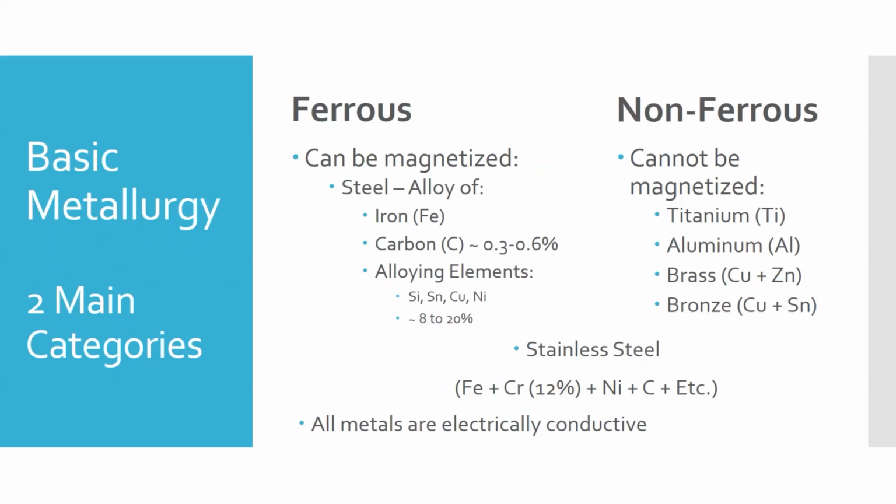Okay. But some of these will develop a temporary magnetic field during the inspection process, like when we do eddy current testing. That induces a magnetic field in any of these, but that magnetic field only is there while the probe is on the part. As soon as you pull it away, that magnetic field collapses. It doesn't maintain.